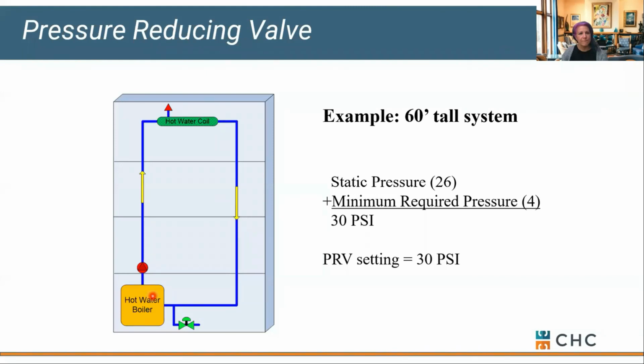But system volume would be the same, temperature change would be the same. It's just that little pressure change that you'd have to account for. Just be wary that if you're putting equipment in the basement and you've got a pretty high building, you might see some elevated pressures in the basement, and that's something to watch out for.